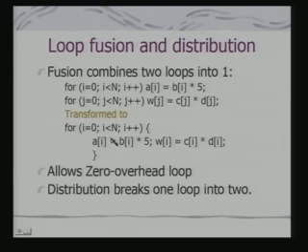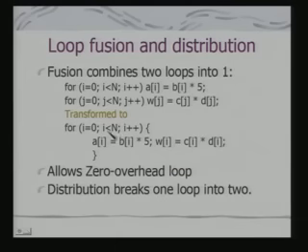In fact, another interesting thing is that once we have done this, I can reduce it to zero overhead, because if you remember, many DSP processors have support for zero overhead loops. You have to initialize the corresponding counters or registers with the number of counts, and the loop implementation is provided in hardware itself. So, once I can do this combination, I can further optimize the code depending on the architecture that I am using.